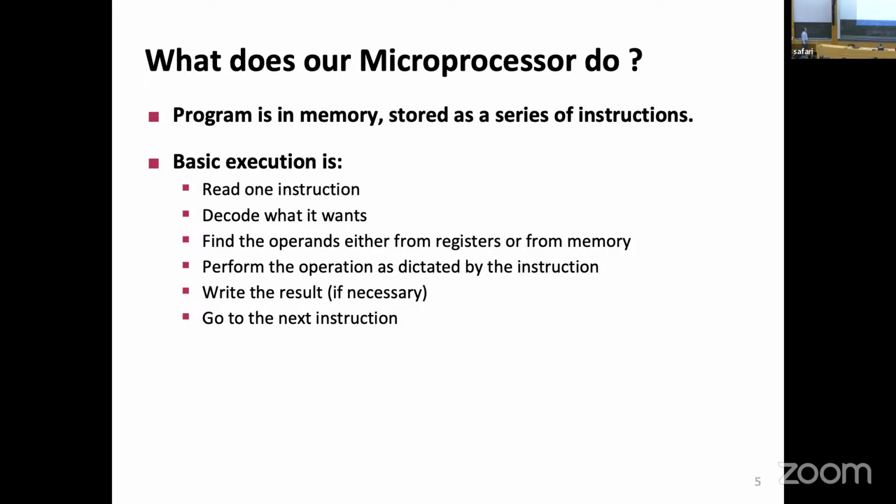Now we need to start over. So this program counter has to point to a new address. How we did this is we also manipulated this program counter. We said, hey, you need to be added, and I need to add the constant 4 because we have word addresses. We take that output and make it the next PC. So this is the PC, this is the PC next, and this is PC plus 4. And that's it. That would take care of this thing.